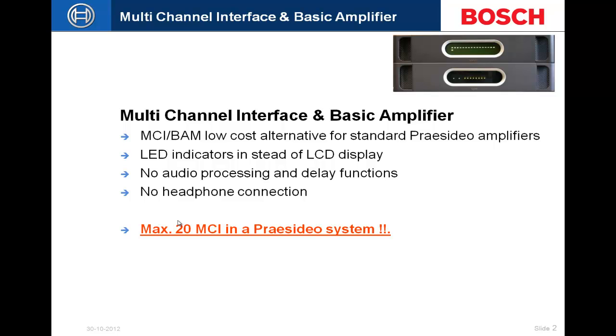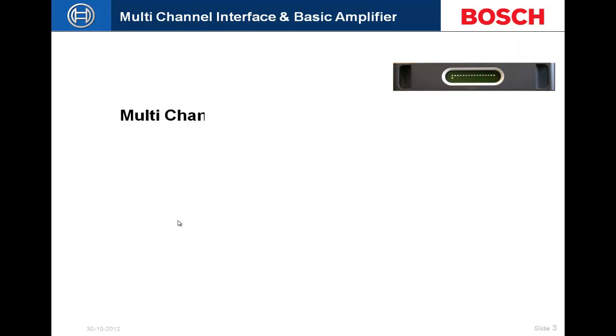Each amplifier is going to have a local audio in, but that local audio in is a low priority input and is directly tied to the amplifier's output. Now, that can be handy in a number of situations, but that audio input does not end up in any way on the system bus.